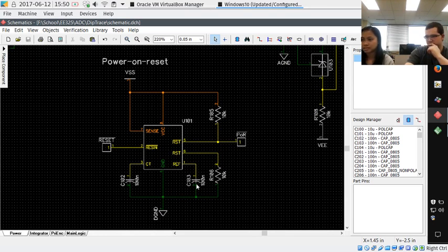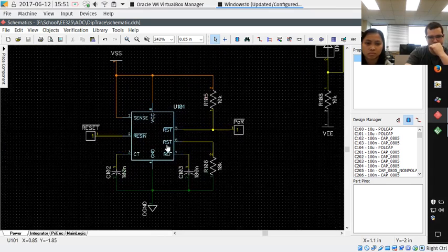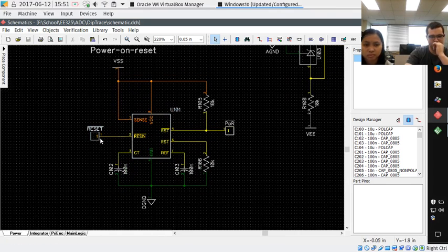We're going to transition over to some of the analog design elements of this circuit. We're starting with power on reset. This senses the digital voltage, and in case the digital voltage is too low, it resets the digital system. Basically, there's this input here that detects whether the user asserted reset or whether one of the analog supply jacks is disconnected, and it will reset the digital circuit.